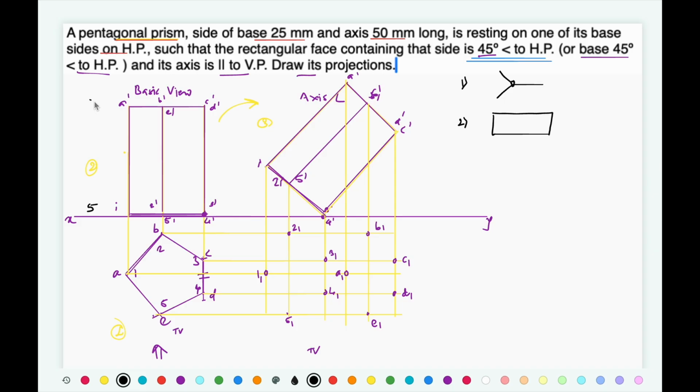There is pentagon at the top, number of edges 5, and a vertical edge connecting one of the corners at the top and one of the corners at the bottom, so there are going to be 5 vertical edges. So there are total 15 edges. Okay, so we need to draw 15 lines in this top view. Okay, so the outermost lines, what are those lines?